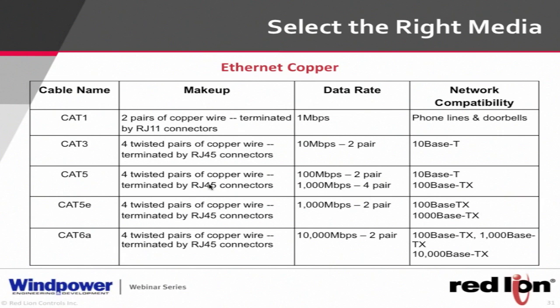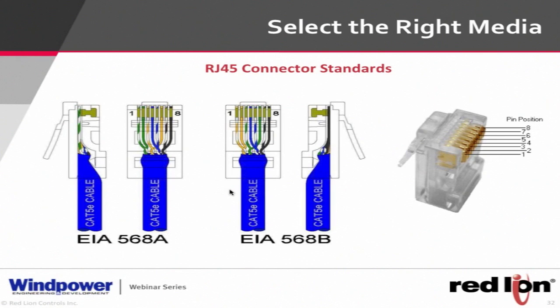Like I said, we're not needing a whole lot of bandwidth on most of these applications. We just need a lot of packets per second to be able to process. And so Cat 5e will work in most all applications. If somebody pushes and says, okay, we're going to put Cat 6a in, that's fine. It'll still work just the same. Just know that the cable itself and actually punching the cables down and all that kind of stuff will probably cost a little bit more. Not a lot, but a little bit more. But it's not always needed.